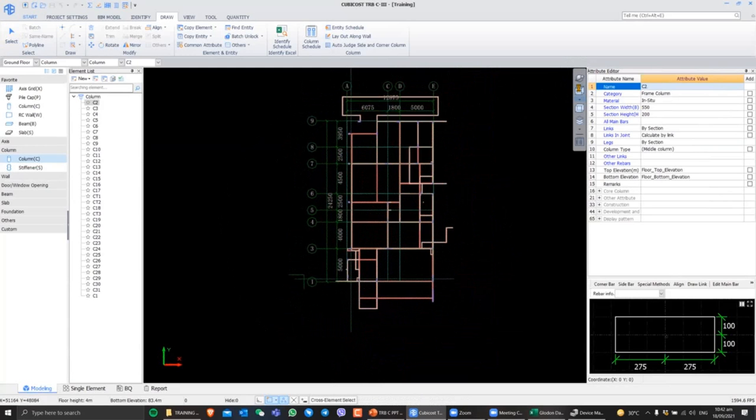Just remember, guys: if you upload a file from TAS, it doesn't necessarily mean everything will show. The finishes, roofing, steel structure, and excavation will not show. The only things the software will show are the concrete elements, because we are only doing rebar here. So all the concrete and masonry elements will show. Just a disclaimer, in case you wonder in the near future why not everything showed.